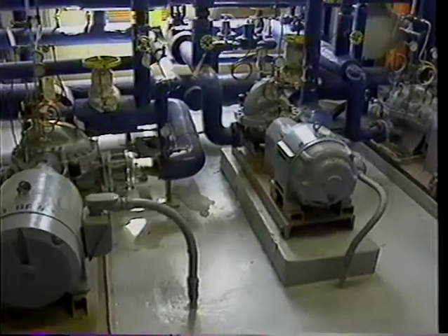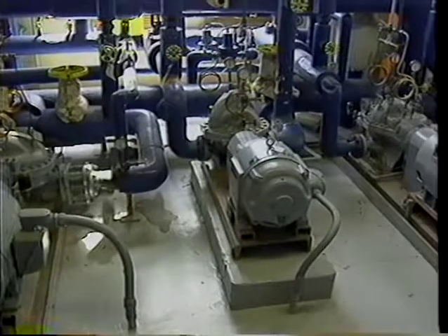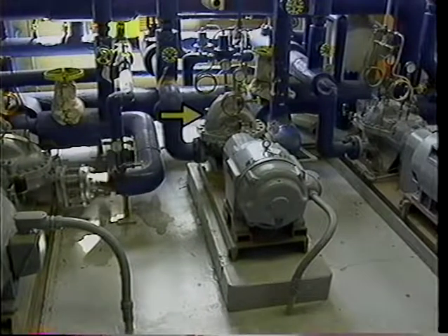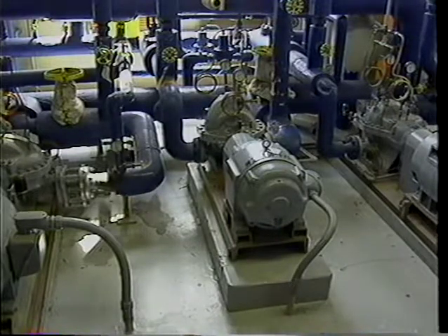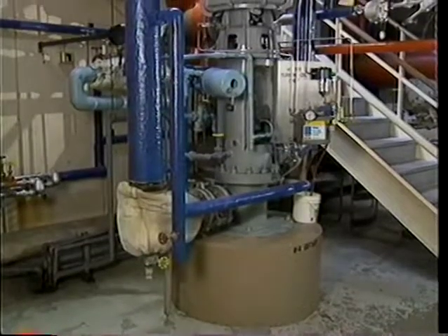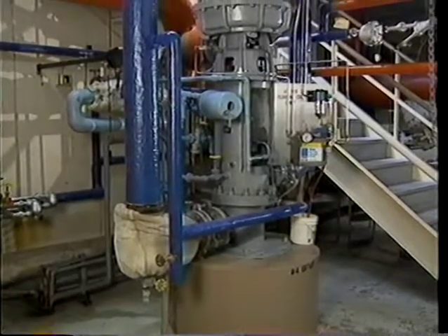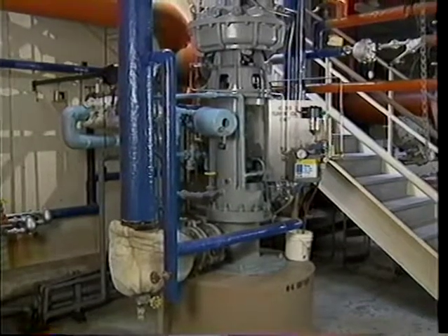Centrifugal force moves water to the outside edge of the rotating impeller. The casing directs water from the impeller to the outlet. Discharge pressure is dependent on impeller speed. Turbine feedwater pumps are steam-driven and operate similarly to centrifugal feedwater pumps.